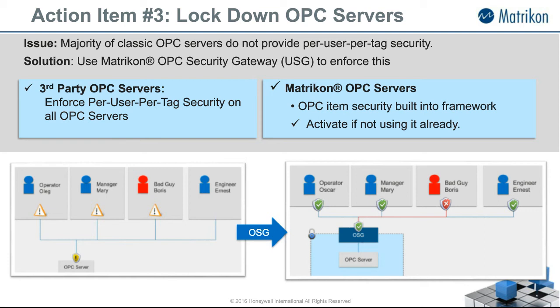And again, it can wrap, like the blue box shows there at the bottom, one or more OPC servers sitting on a PC. That way you set up the settings on the server so they don't accept connections from any other applications, and they'll only work with the security gateway, and therefore everybody has to go through the security gateway, whether it's local or remote. This also is compatible with the tunneler software, so on top of that you can of course have the data encrypted, and you eliminate the use of DCOM.